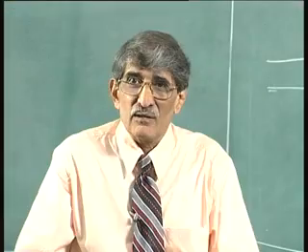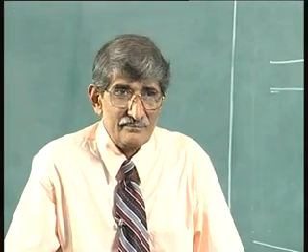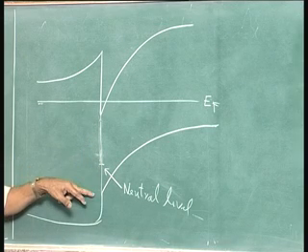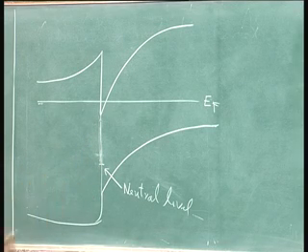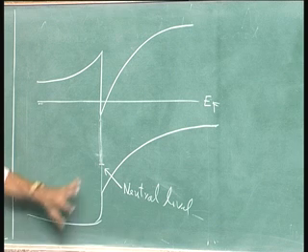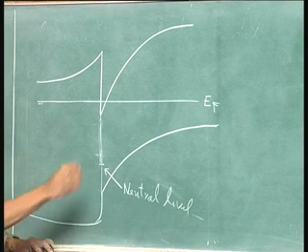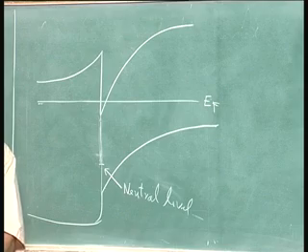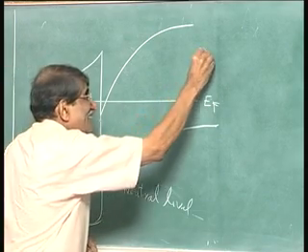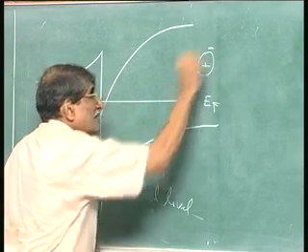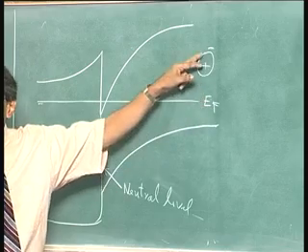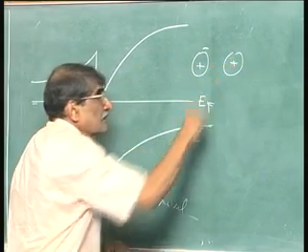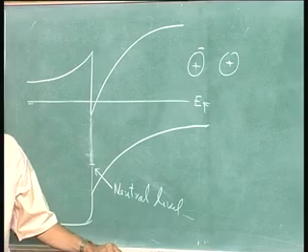That is unoccupied by electrons. But when it is occupied by an electron, that hole has gone to the valence band. That is negatively charged. When we say occupied or unoccupied, we mean occupied with an electron or not. When it is occupied by an electron, the hole which was occupying that has left the place. That means an electron has gone there, so it is negatively charged. That is why an occupied acceptor level is negatively charged. All of them are negatively charged.